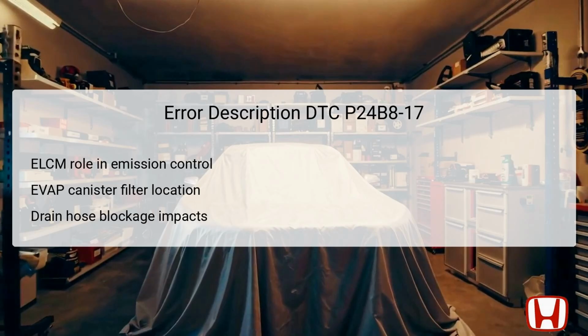It is also important to note that blockage in the drain hoses could falsely trigger this code, so both the evap canister filter and drain hoses should be inspected as part of the diagnostic process.